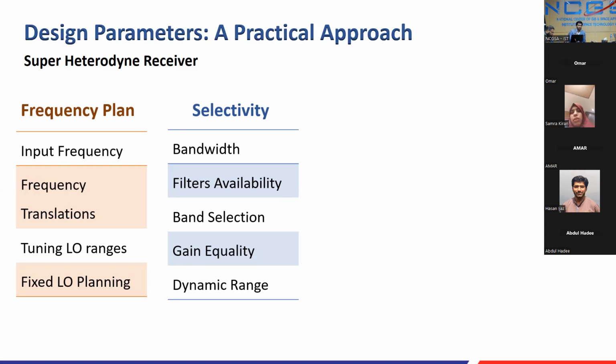He might tell you his input frequency, but there will be a complete RF bandwidth, and then there will be an instantaneous bandwidth. We will come to that later, what the difference between the two is. Then, if your receiver is at lower frequency bands, from 100 MHz to 1 GHz, you might have to think about filter availability and roll-offs. If adjacent bands are too close, you need very sharp roll-off filters. Microstrip filters won't work there. You have to accommodate cavity filters, resonant cavity, iris-based filters.